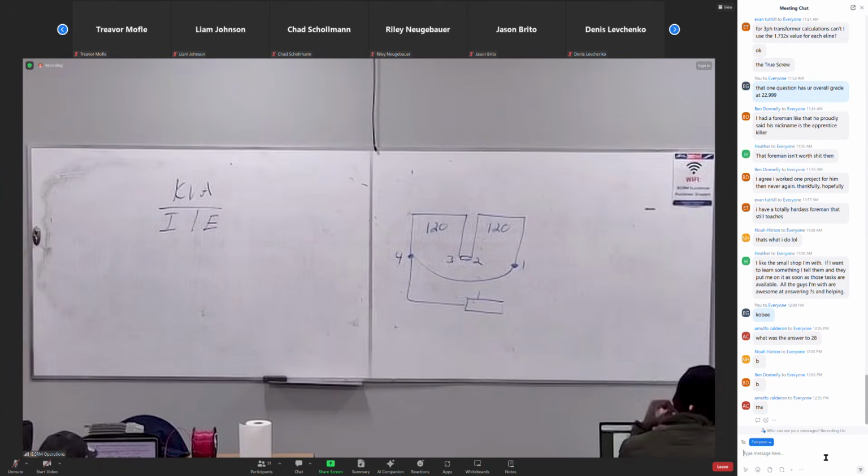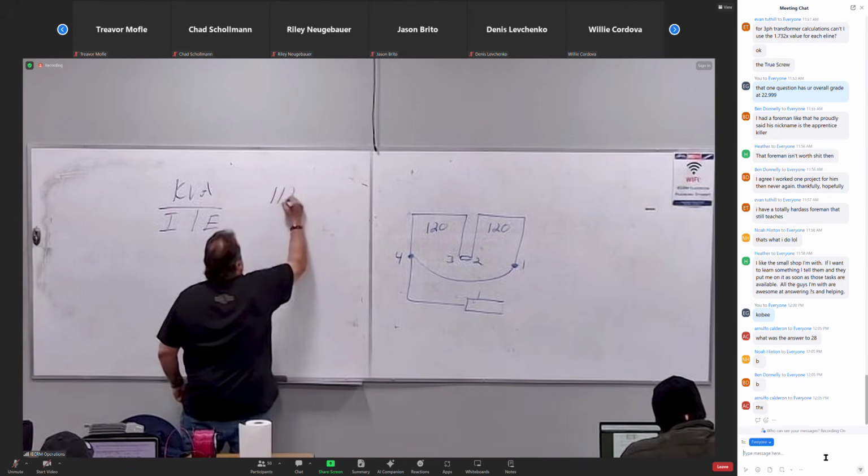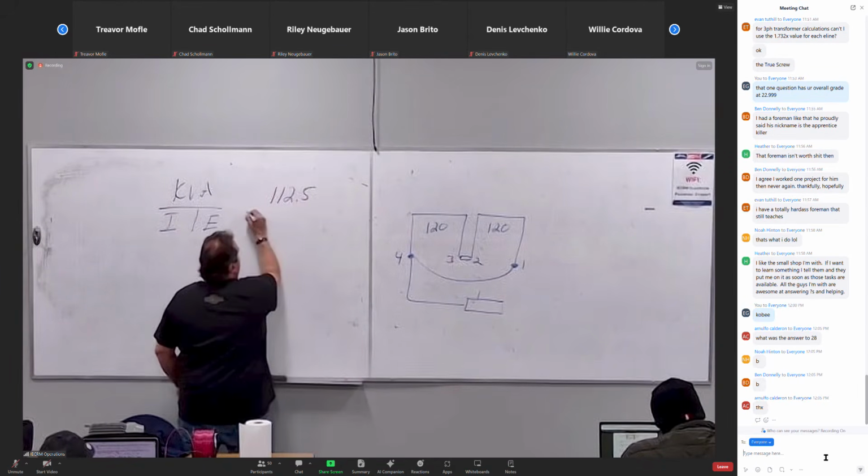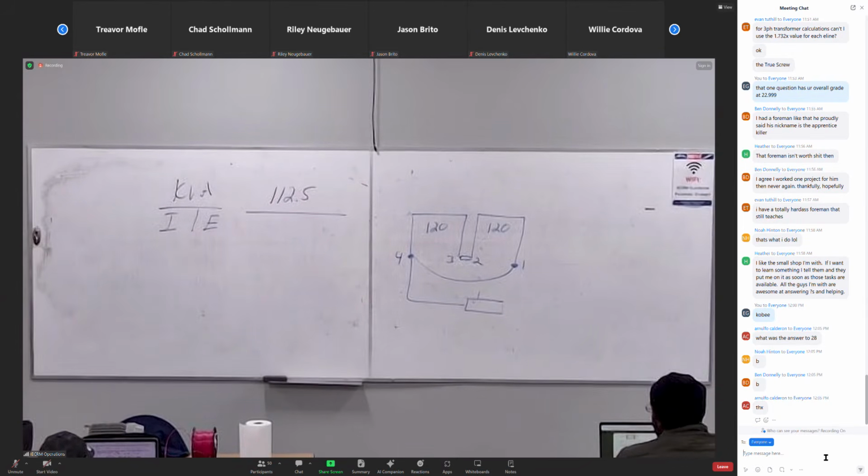Okay, what did my question say? You said that was 38, right? It's a 480 volt to 240 volt three phase transformer rated for 112.5 kVA. So first thing I know, two things. One, there's two voltages, and the other thing is I know my power. Power in equals power out, so I already have power. What's my power? 112.5 kVA. I already have that part, right?